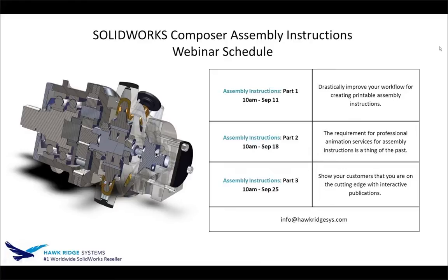Okay, just had a question come in saying, is there a way to insert page numbers to views that update automatically? Yes and no. Within Composer, in the template, you can do that. So you can actually set up a template with so many pages, and they could be pre-labeled, and you just dump stuff into it. And that's the way to do it. If there's any more pages that you need to develop that aren't in the template, you just would number those per page.